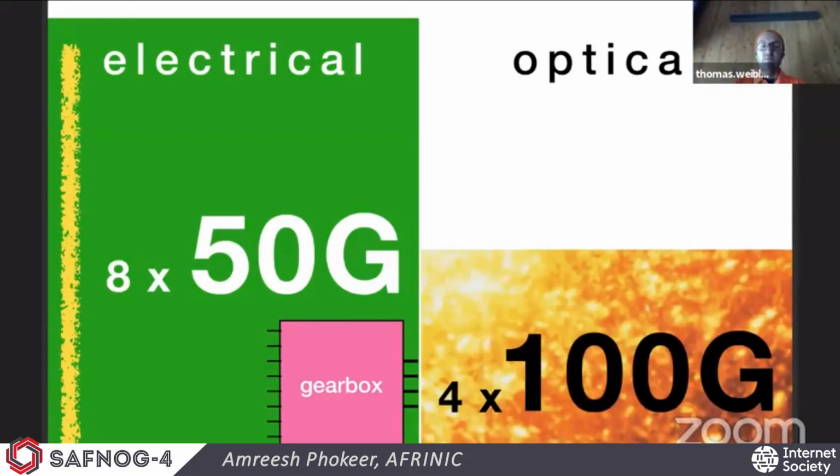And this is quite important because you will see later on the types of applications we can get there. There might be the question now, hey, why don't we just run 4 times 100 gigabit on the electrical side? In theory, this would be possible, but it's way cheaper to put an ASIC into that transceiver instead of having a high-speed enabled 100 gigabit electrical PCB.